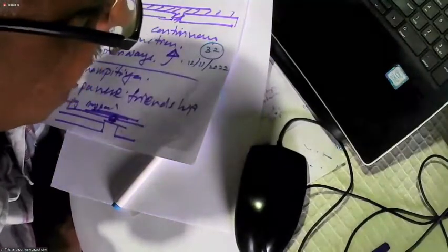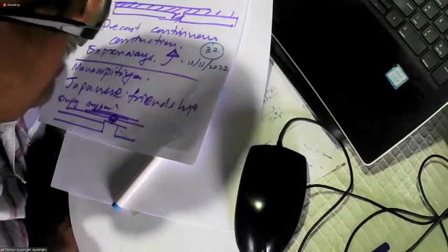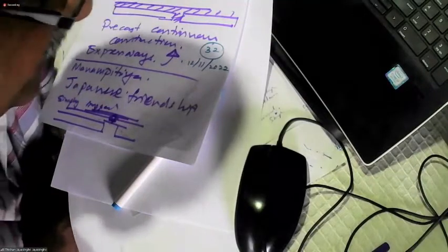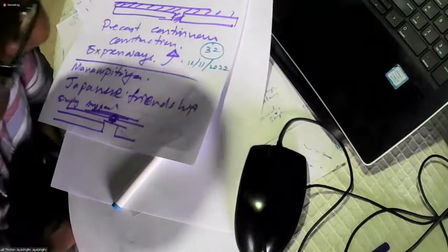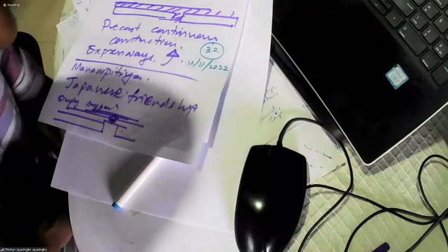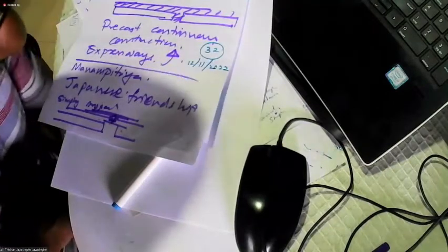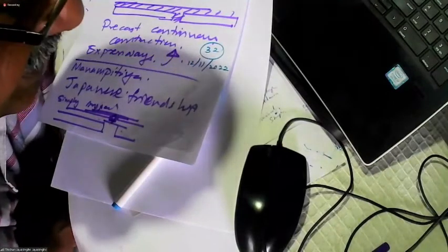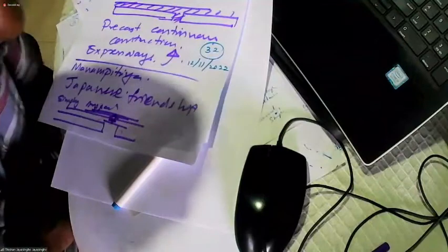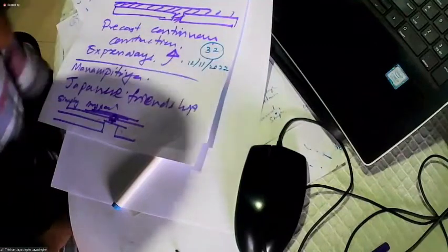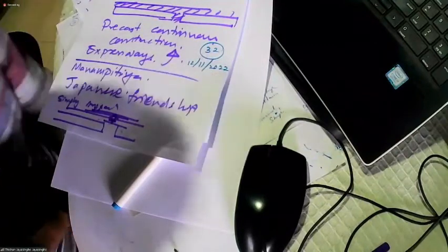And then I talked about continuous beams and showed that continuous beams have an envelope for dead load, and there will be an envelope for live loads, and an envelope for live loads plus dead loads, everything. But what is governing will be the live load range, not the other things.